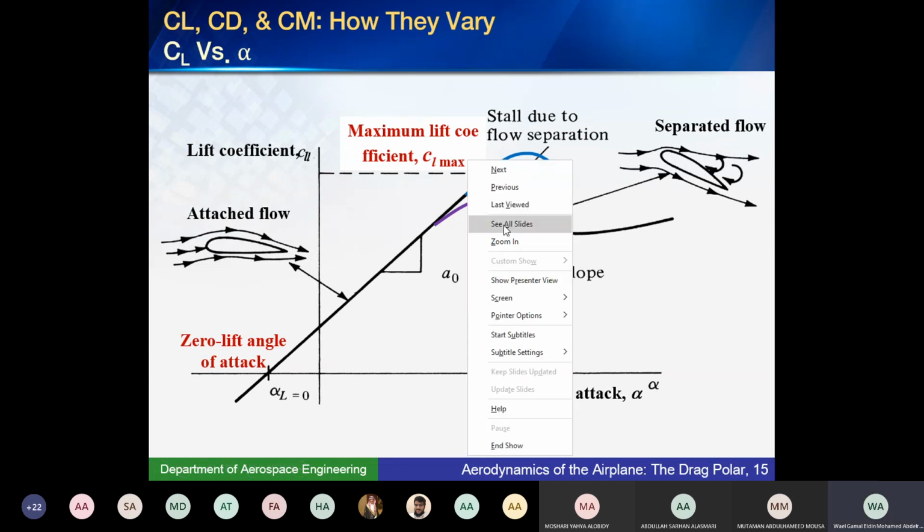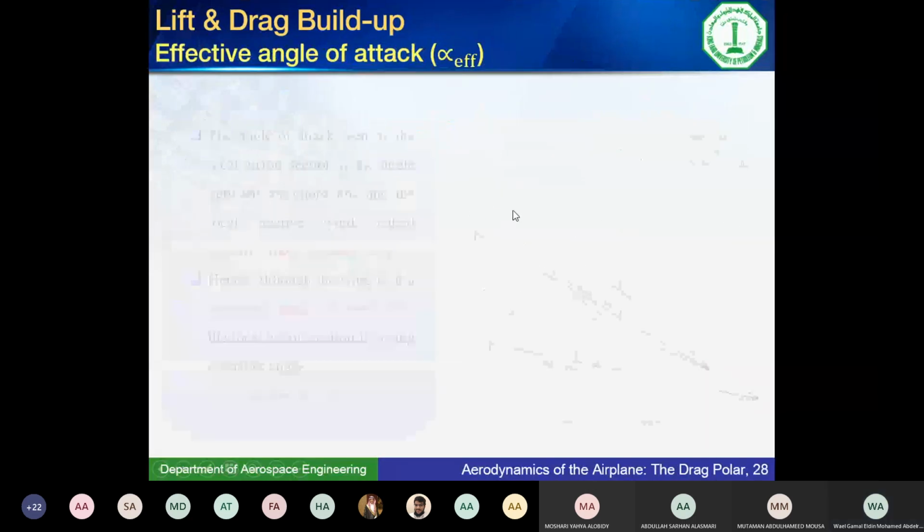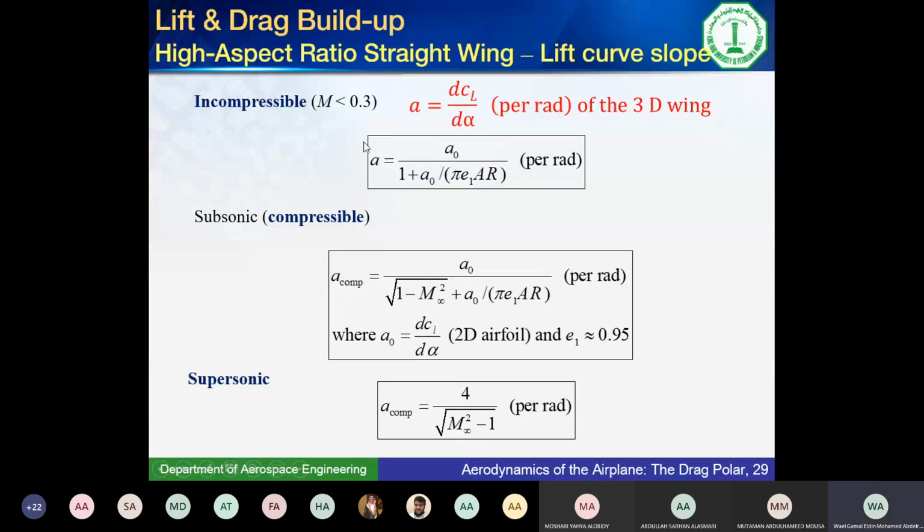Okay, and that's what you had in aerodynamics in AE 220. So I'm just going to present the result here. We had a set of equations that would relate the slope, the CL alpha slope, to the slope of the airfoil, the 2 pi. Think of this as typically 2 pi, the slope of the airfoil. So as the aspect ratio decreases, that means the wing becomes more finite. As this ratio decreases, what will happen is that this value is going to decrease. As it increases, it's going to increase, and so on.